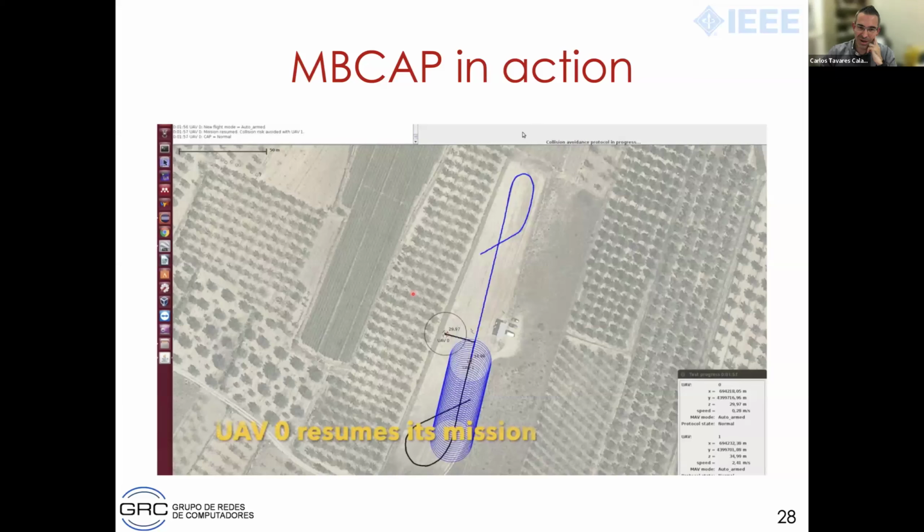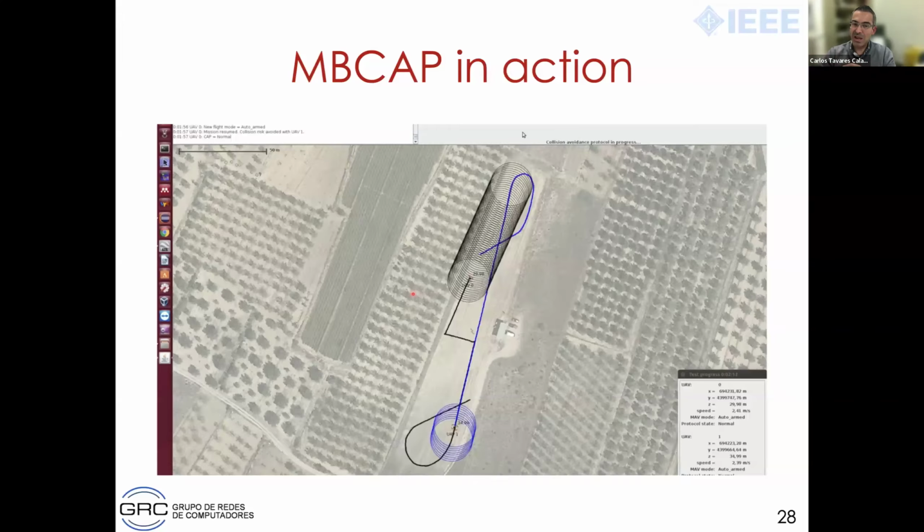So what is different about ArduSim? We are using open source flight controllers, the Pixhawk flight controllers. There are already some drone emulation solutions for the physics part, where you can emulate, using software in the loop, a drone in your computer. In our simulator, we leverage this initial model in order to allow multiple UAVs to be running on the same computer, and then we provide all the communications layer between them. This is running in real time, like a real UAV. So this is not actually simulated, this is emulated, because it is running in real time.